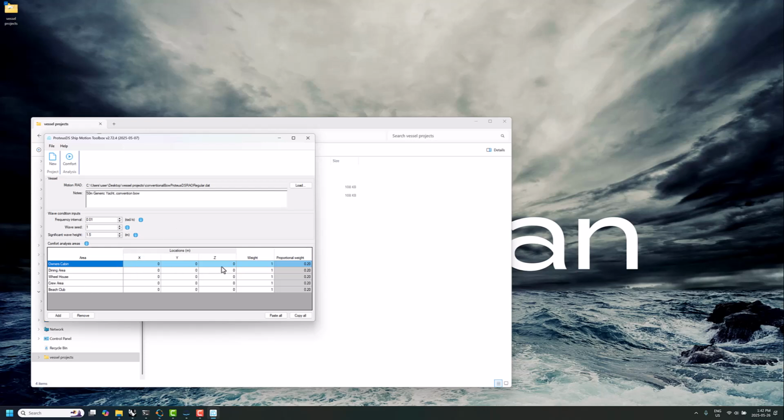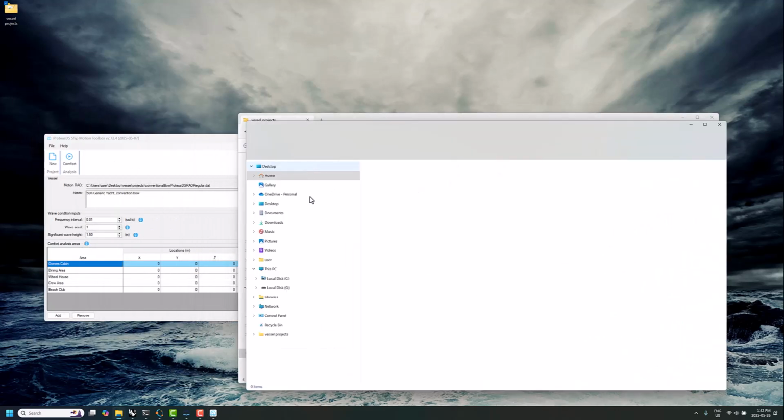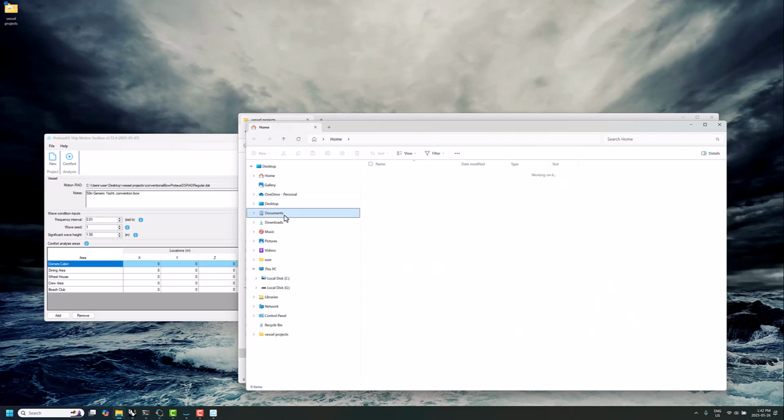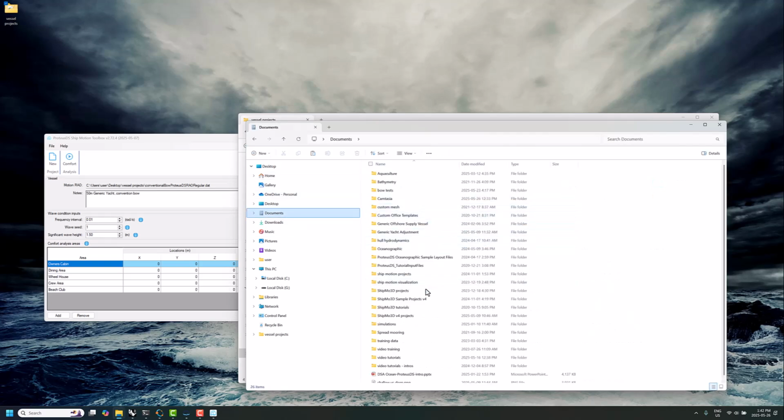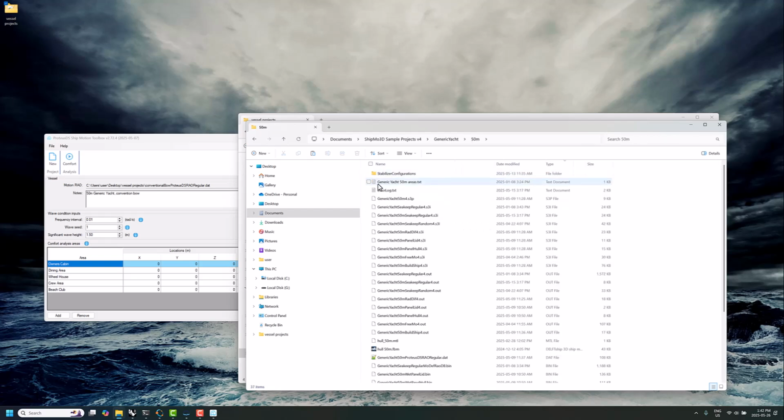Now, one thing about doing a large yacht motion affected comfort rating, you do need to locate the areas of concern. So this is the wheelhouse, dining area, a lot of the crew area, all that kind of stuff. One thing that's nice about the default projects is we've defined these areas for our generic yachts. So if you check out the sample projects, generic yacht 50 meter, you'll see generic yacht 50 meter areas. That's a text file.